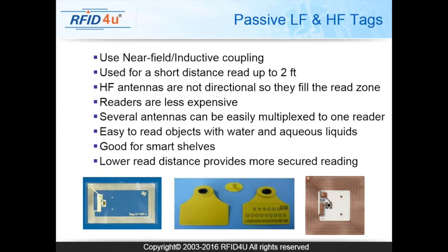So low frequency and high frequency use near field or inductive coupling. It's used for short read ranges, up to 2 feet. More commonly, for example, on your credit cards, based on the protocol, they're only going to read at 1 millimeter. Or if you're using an access card going in and out of a building, you'll notice that you have to get pretty close to that access card. So that's used for short read ranges.